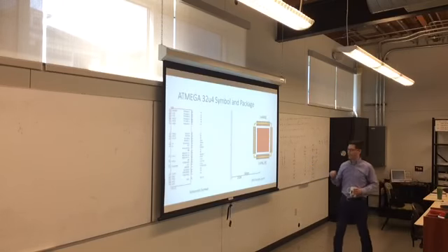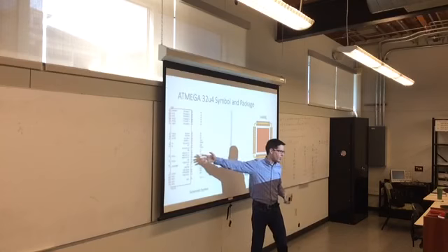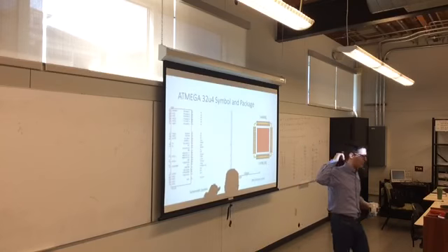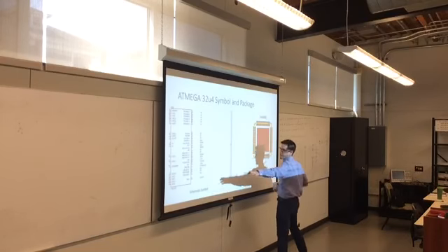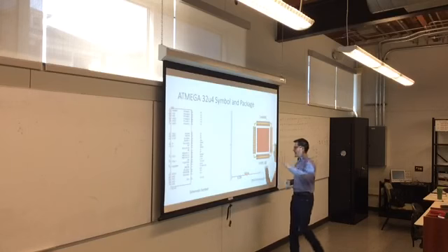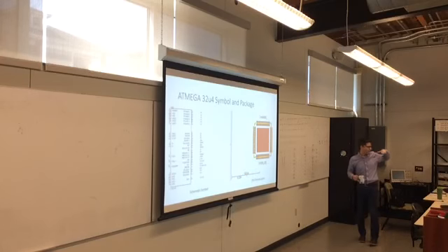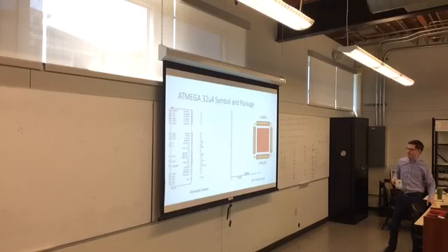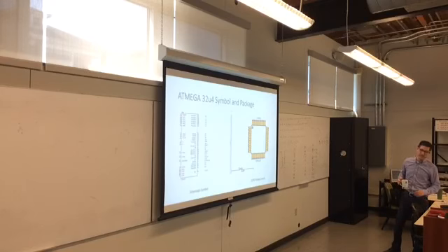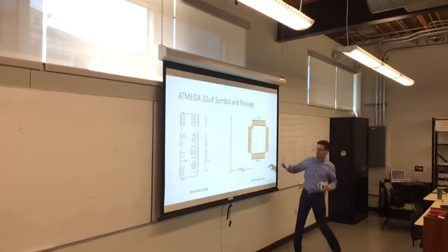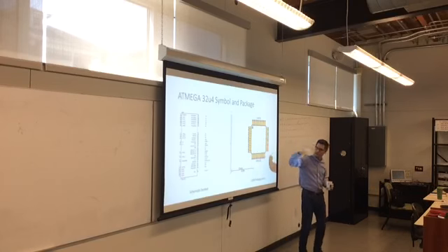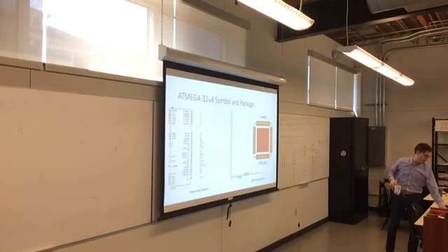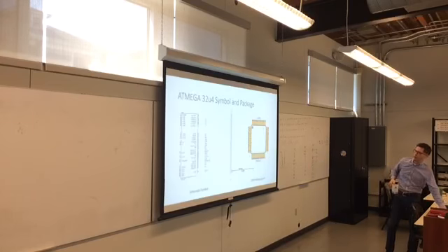When you're talking about pin packages, your schematic can look any way, but that, again, does not imply necessarily what package you're working with. So this, for this ATmega, is a QFN package, which means that it has very small sort of leads attached to it. This is the same device, but this is with a sort of a TQFN package, so the leads are a little bit more exposed. So my point here is that if you look at the schematic symbol, you don't really know, am I dealing with this chip or this chip?